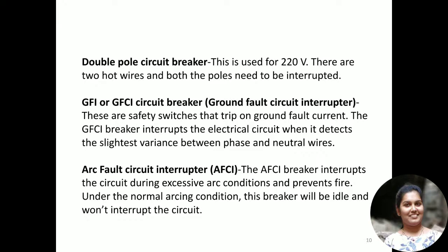Next one is GFCI circuit breaker. GFCI means ground fault circuit interrupter. These are safety switches that trip on ground fault currents. The GFCI breaker interrupts the electrical circuit when it detects the slightest variation between the phase and the neutral wires. So if any small variation between the phase and the neutral wire is detected, the electrical interruption will be made with this GFCI circuit breaker.